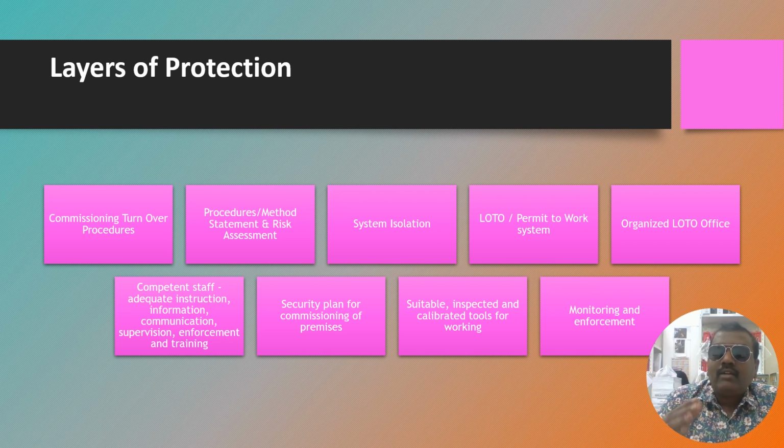And the 240 feeds to one main light distribution board, and that board can feed another lighting panel, which will have an individual breaker for individual lighting fittings. So the final is the light fitting. In this condition, each and every breaker is to be locked one by one, and using the notice of energization, this padlock is to be removed and energization can be done site-wide.